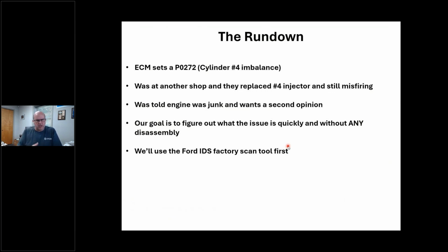Okay. And we want to give him a second opinion here at Lakeland Auto and not spend a bunch of time on this, because we don't know if he's going to fix the truck. So you know what my goal is? My goal is I want to back up. He was told that he thought the engine was junk. The previous shop did not have the compression test adapter to go into that cylinder, verify it had no compression. Okay. So we want to figure this out.